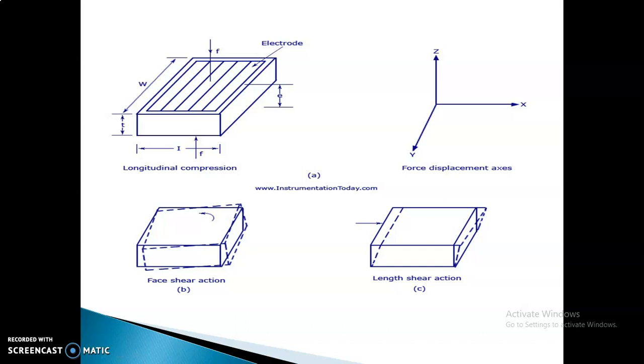Generally for the piezoelectric accelerometer, people go for shear mode operation. Shear mode operation gives you high sensitivity as well as a larger movement for less energy. That is the reason shear mode operation is used.